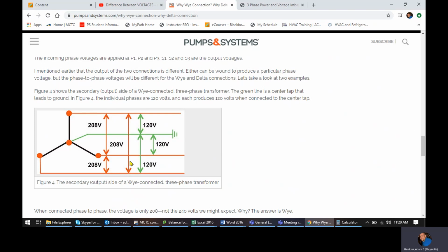That's why when we tap most of those units off in that room, we're just grabbing two legs of the three, and that is actually a two-phase system. I said you don't really see two-phase, but the way that we're doing those in lab is actually two-phase. You're grabbing two of the three legs, knowing that each one is 120 volts, and you're doing it on a 208 circuit. We're having to make it work in lab because of the way our power comes in.